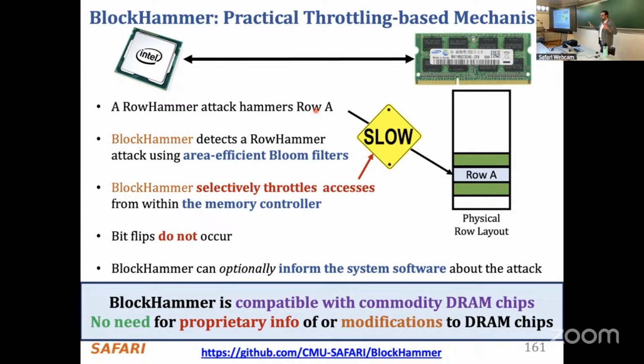In a DRAM module, you have multiple chips. So this is a picture of a DRAM module, right? You have 8 different DRAM chips here, and in some modules you have extra ECC chips as well, so that if one of these chips fails, you can correct the bit flips. So they shuffle the rows in a way that the shuffling is not the same in any two chips. Every chip has a unique row address layout. When you do that, as a result of a RowHammer attack, your bit flips are accumulated in a single chip. And if you also employ rank-level ECC on top of that, then you can correct the bit flips coming from that chip, and you can mitigate RowHammer to some extent.